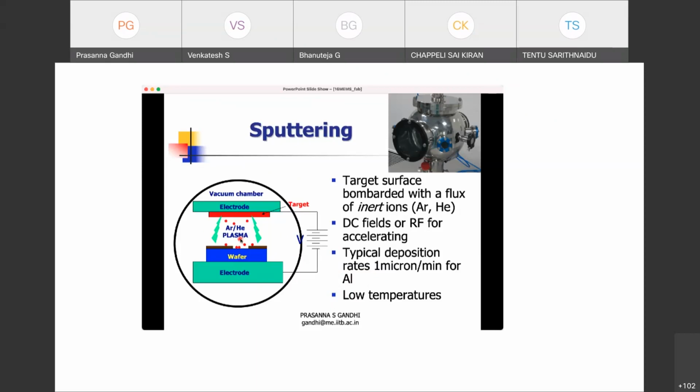Alpha, the coefficient of thermal expansion, if it is not the same for both materials, they will cool down by the same temperature but contract differentially, and that differential contraction is going to create stresses in both the materials.